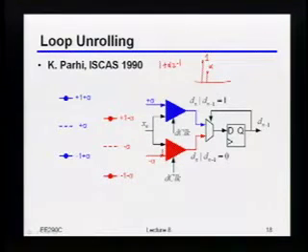Okay, so I wanted to spend a little bit of time on what these different levels look like, because you'll sometimes see eye diagrams with these loop unrolled DFEs. By the way, in communication terminology, this is sometimes called a partial response channel, meaning that you're not canceling all of the response, but you're leaving some amount of intentional ISI there that you're going to deal with later. If you look at the eye diagrams for these things, they tend to look, let's say, funny. Because there are basically 4 levels in the center of the eye, and then a whole bunch of transitions that can potentially happen on the edges.